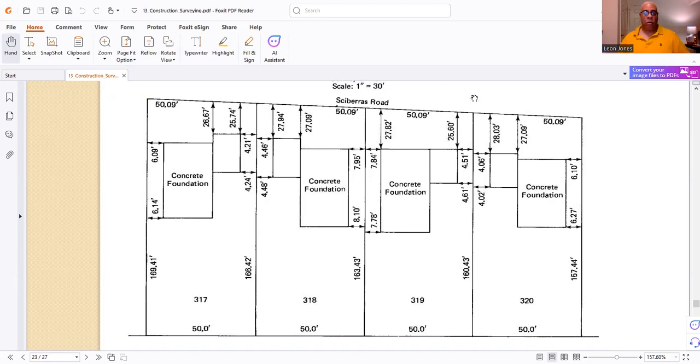Now, when you deal with a road, buildings all have a setback. Why? Because when it comes to the road, there's right of way. Now, what is that right of way used for? That's in case the road is going to be widened. Now, sometimes DOTs buy right of way. That's what eminent domain is for. But you see in this plat how all the measurements are done.